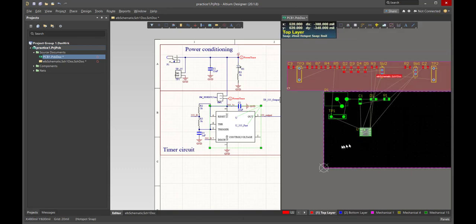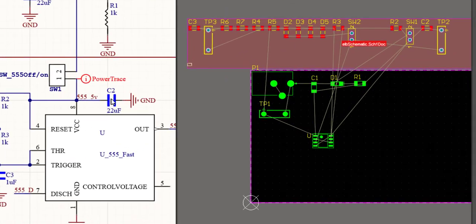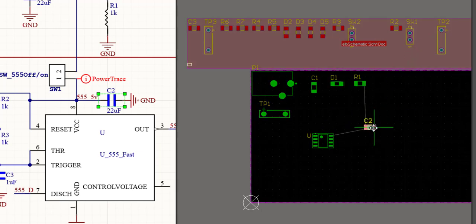After we put the IC down and we have a good orientation, the next thing we want to place is its decoupling capacitor. So we're going to come and grab our decoupling capacitor, and there it is. Now, if I had clicked on the other side of that part, I'm really not clicking on the part, I'm clicking on the terminal on that side, and you can see only one terminal is selected. And so you want to be a little careful when you select the parts that you click on the part itself. And now I've got the part, which means all of its terminals.